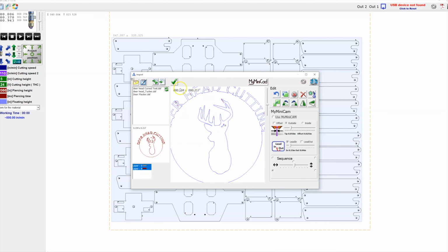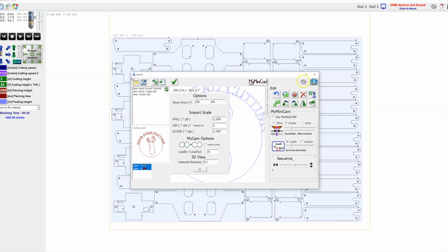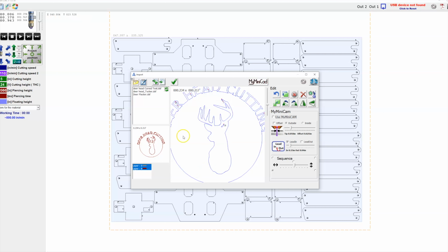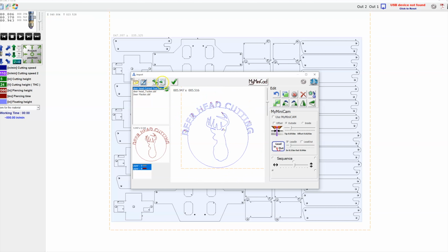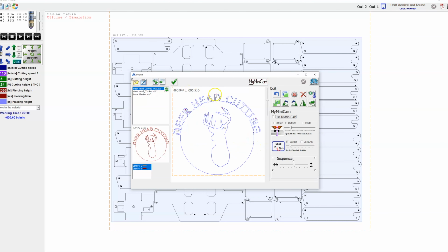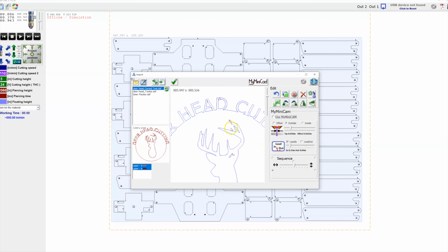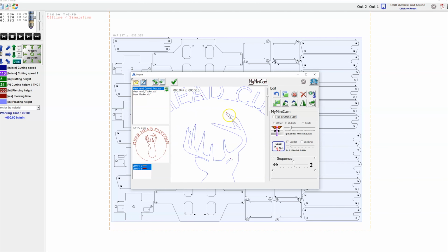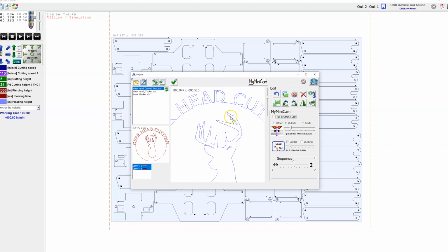And notice it's very small again, so I'm going to go into here, change this to 25.4, okay, and then now I'm just going to click it again, send it in again. There we go. Now we're 5 by 5. And now you'll notice that my lead-ins, I need to modify these a little bit. We have some straggling pierce points, so I'm just going to take this and drag it a little bit smaller, and you should see some of these lead-ins populating.